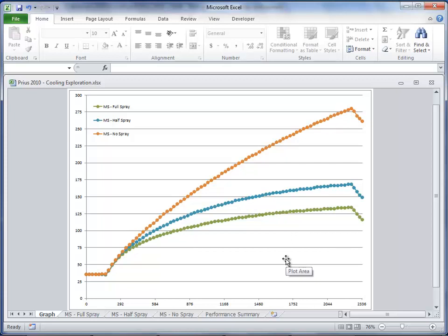The Prius is a very interesting motor for many reasons, one of which is that they have automatic shutoffs for the power or the drive associated with the winding when the winding temperature gets too high, and that can be preset or set differently depending on performance. But Oak Ridge National Lab chose to stop this test so that the winding would not get higher than 135 degrees.